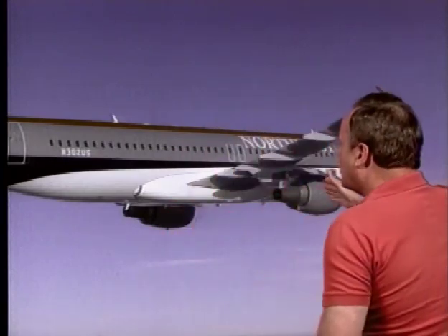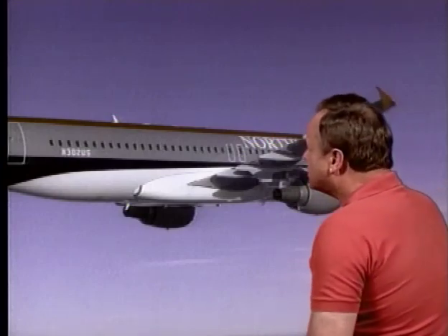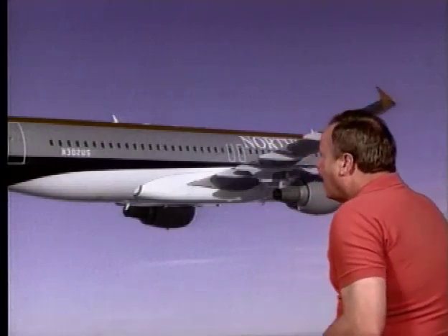Now, let me ask you a question. If you have warm air, is that air more or less dense? And the answer is that air is less dense. So you turn on engine anti-ice, you don't change anything else. Is that engine going to produce more or less thrust? And the answer is, well, you got hot air coming into the engine. It's less dense. The engine's working on thin air. You're going to have less thrust.